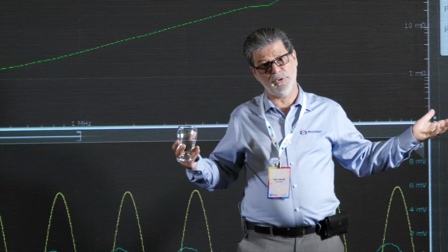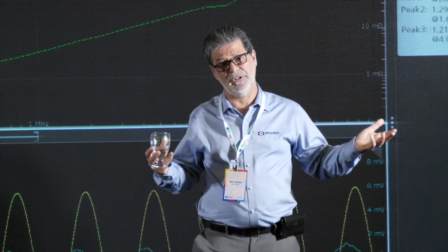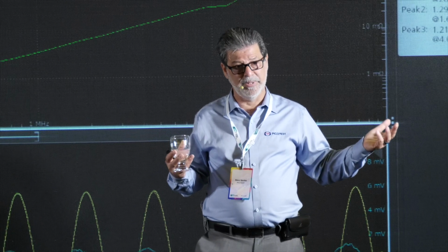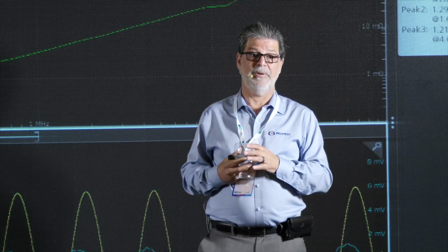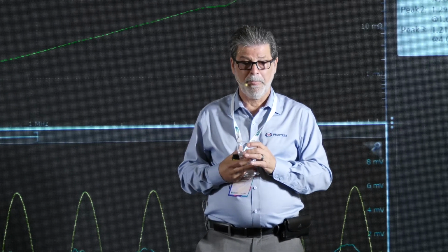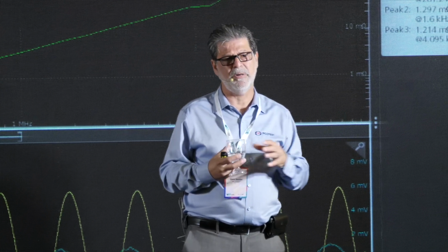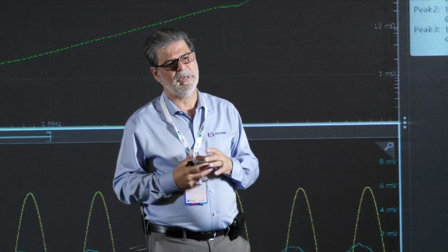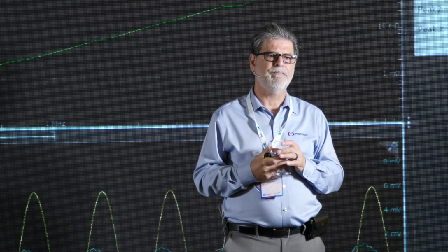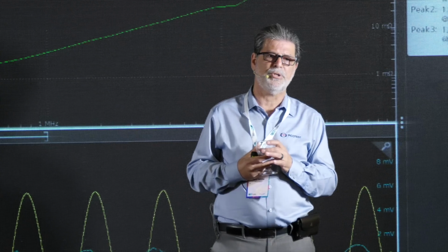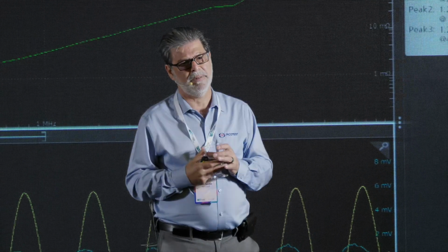And so the higher you go in switching frequency, the smaller the devices are going to be, and the better the performance can be, with the exception of efficiency that's going to suffer. There are many switching regulators now up around 100 megahertz, 150 megahertz. We're hoping to get to a gigahertz in the next couple of years. I don't think anybody's accomplished a gigahertz switching, but we do hope to get there.